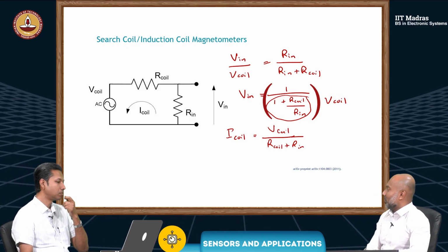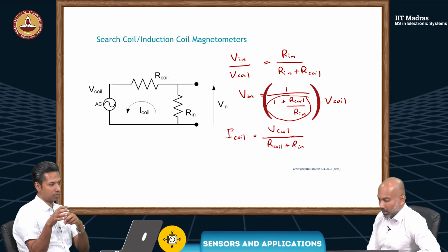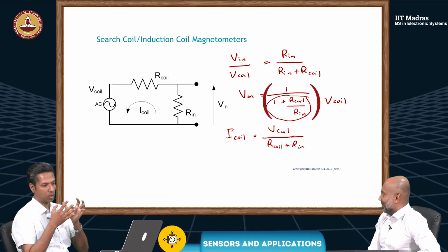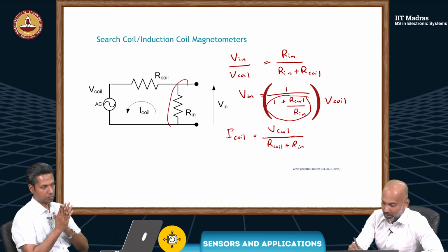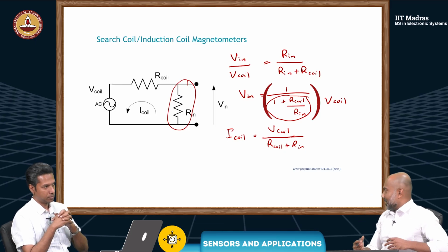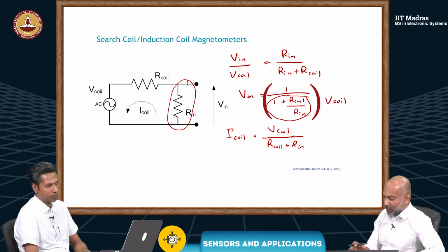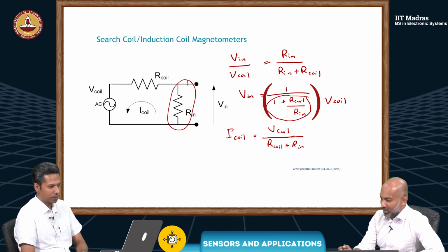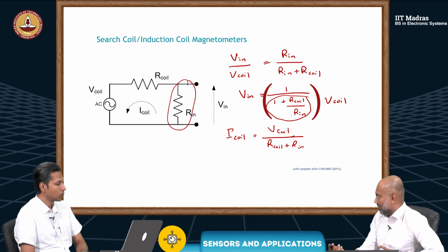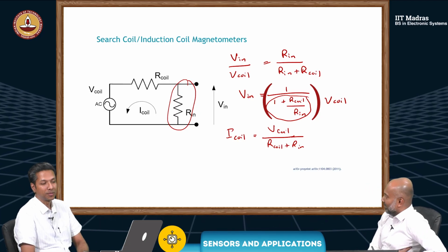So now already it's producing a reduction, right? This R in is the input impedance of something that you are going to use to measure, like a preamplifier or an acquisition system. Yes, this R in, this part here. Okay, so it seems like it's getting harder and harder, with more variables. If you look at it a bit closer, you also see the output is reduced by a factor of 1 plus R coil over R in. Any other things you need? No, I'm good.